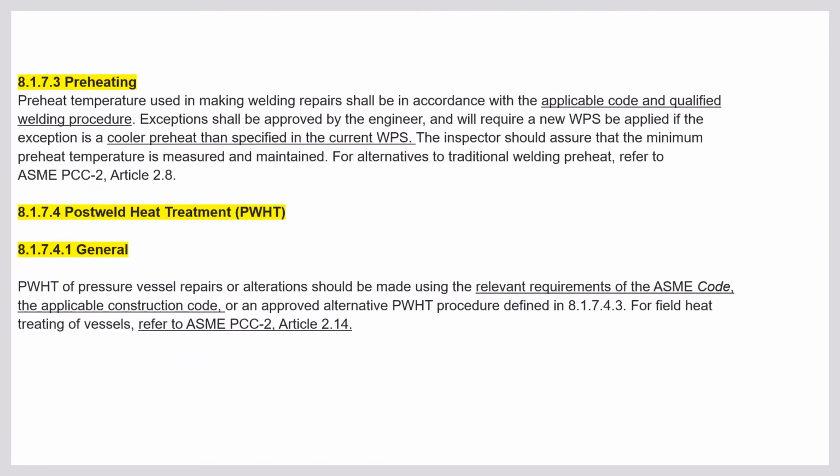Preheating. What is the preheating requirement? Preheating requirement used in making welding repairs shall be in accordance with the applicable code and qualified welding procedures. That may be a question. Preheating should be done as per ASME Section 9, ASME B31. They can put whatever they want, and they will put another term: as per the applicable code and qualified welding procedure. So that is the answer you have to mark. Okay. And PWHT of pressure vessel repairs or alterations should be made using the equivalent requirement of the ASME code, the applicable construction code.